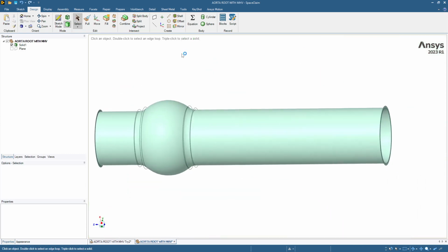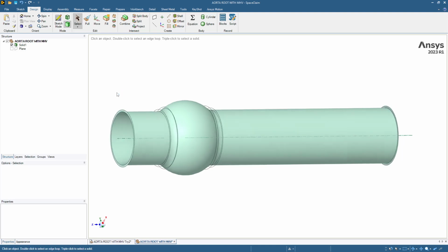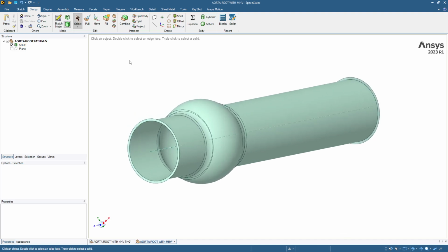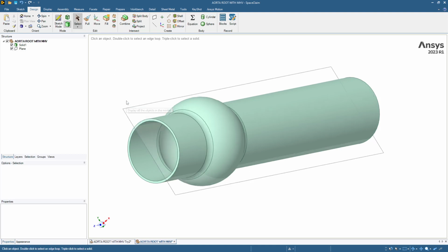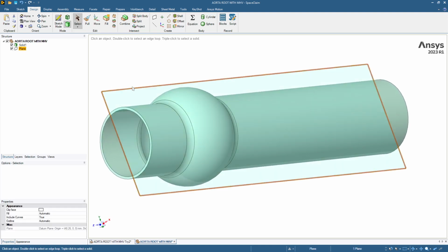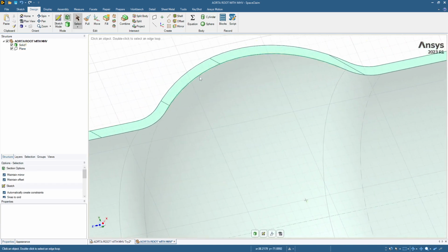And if I, these surfaces represent the inside of the fluid volume, I could just delete these end faces and we would have a fluid volume, but I'm here to demonstrate how to extract the fluid volume. So I'm going to show all, so we're looking at the outside faces again, but now we've gotten rid of that step in the wall.